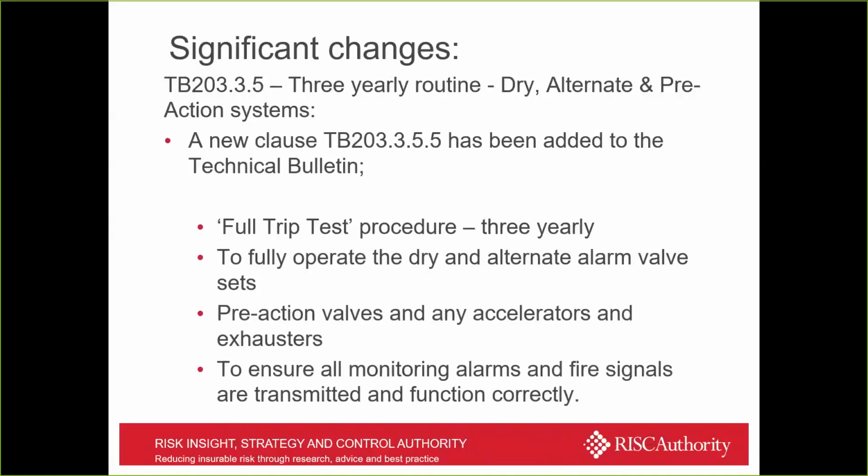So you do a full fire test basically, and that allows you to test both the valves are operating and the alarms and the fire signals are also transmitting correctly. So that's a full fire test basically, as opposed to just exercising the components of the valve.